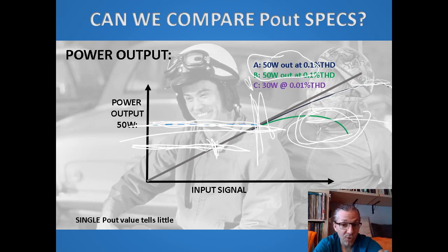So when you look at a really high power amplifier like a D'Agostino amp, and they say this puts out a kilowatt at 0.1% THD, it means that amp will still be comfy playing at 2 kilowatts, because then it will have maybe 0.5% THD, but it's not keeling over yet. And if they had specified 1 kilowatt at 1%, it really means that you are already pushing your amp to the point where it's ready to let go.